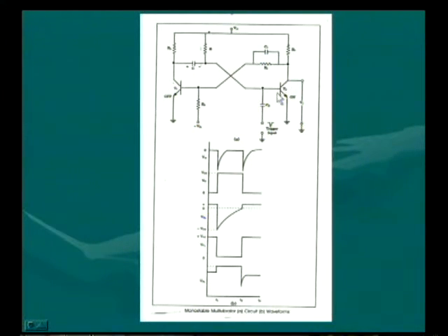So here transistor T2 is on, whereby the voltage is 0, which is input to the transistor T1, and in conjunction with that here we are having some minus VBB which keeps the transistor base emitter junction in reverse bias condition, hence transistor T1 will be held in off state.